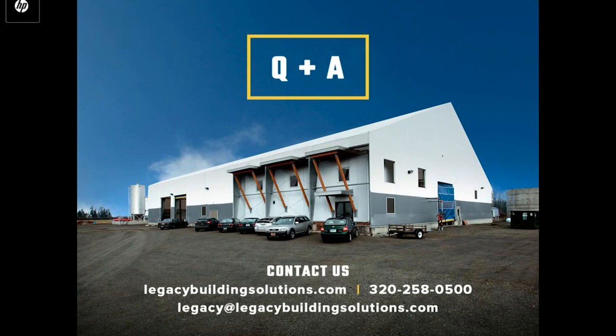A question here about insulation. What is the R value if you only use a liner without insulation? That is a good question. It's probably up to interpretation a little bit, but a building with a liner and no insulation really technically has no R value, or it's R1 or 2, but it's not significant. That's why most insulated buildings that we're involved with, we use R30 insulation to provide a very good basis for heating the building.